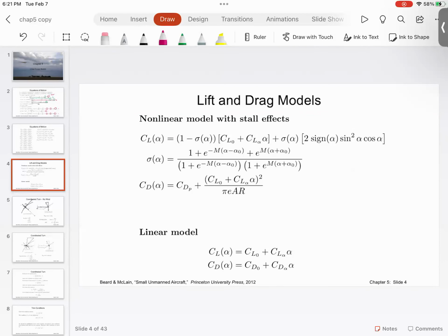This is something that we talked about in last class. Usually we don't do it in simulation, but if you want to include the effect of stall, which means something like this: the aircraft is flying, the aircraft is pitching, and after a certain pitch, it actually falls down, because the aircraft can no longer generate the lift because there is a flow separation on the wing. The aircraft goes forward, pitches, and all of a sudden flips down. So basically that's stall.